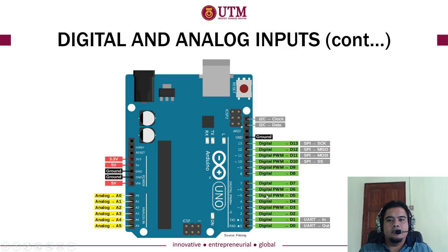The one with digital PWM can support analog output. But for digital output, it doesn't matter, you can use any pin from 0 to 13.